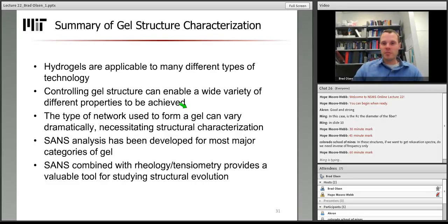But going back to the beginning, the definition given by Richard Jones, many different types of things can form a network in a material. And when you form a network that's capable of bearing mechanical stress, then you have many different ways to form this gel. You can do it by linking together flexible polymer chains, something you envision like a net. You can do it by linking together rigid self-assembled fibrils, by self-assembling block copolymers, by building structures such as nanocomposites or jammed colloidal structures, all of which can potentially bear and transmit load through a network. And these networks can be formed covalently or non-covalently.